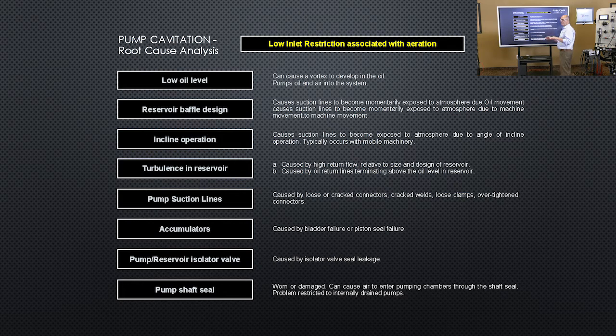Incline operation: again, we have to be very careful that we don't exceed the manufacturer's recommendations for incline operation. Next is turbulence in the reservoir, created by high return flows due to the volume differences in cylinders, or discharging oil from accumulators. Pump suction lines: we could have loose or cracked connectors, cracked welds, loosened clamps, etc.